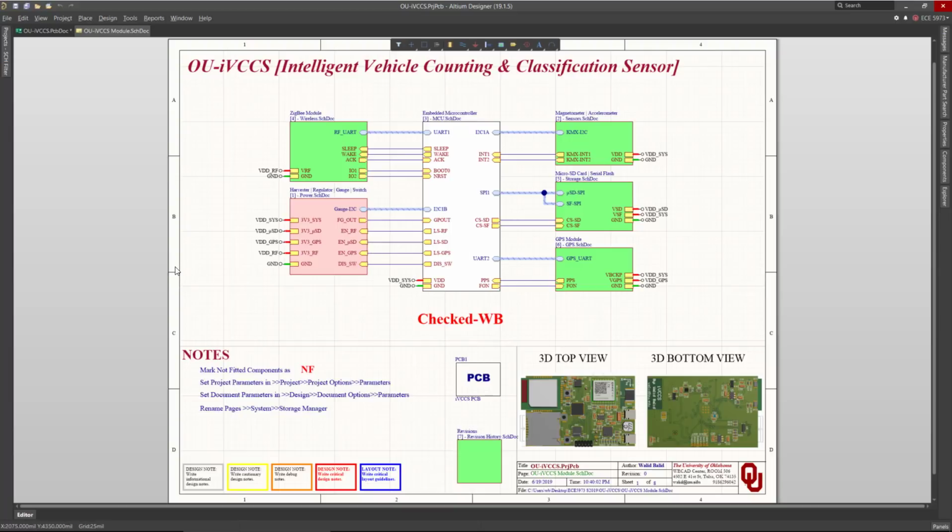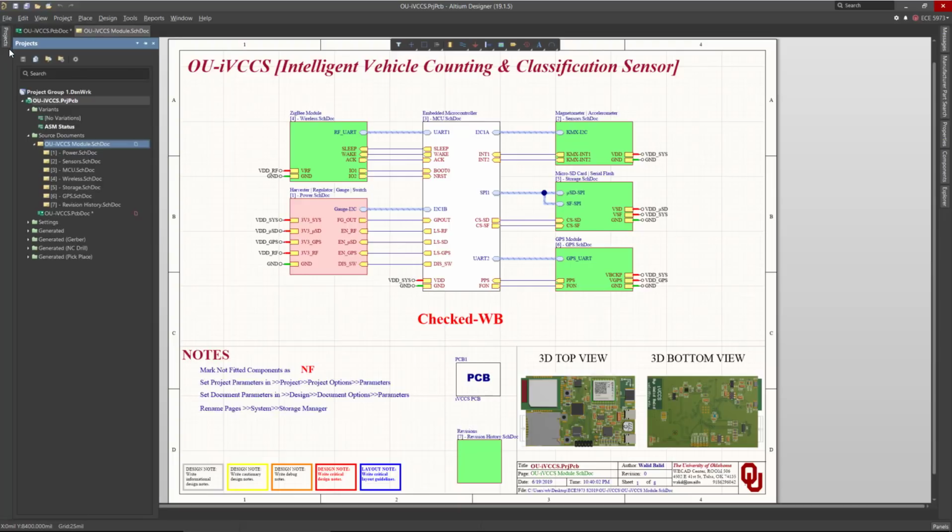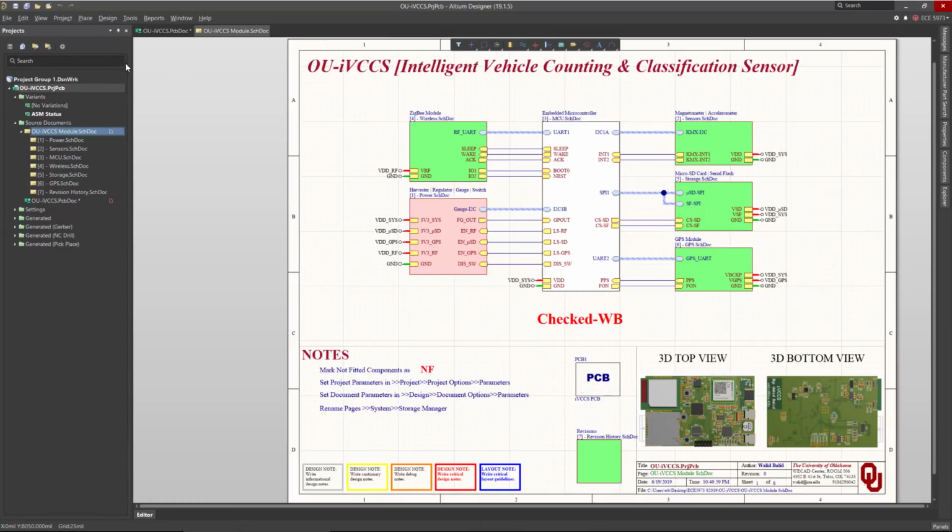Let's start with docked panel mode. These can be docked horizontally or vertically within the main application window. So if we click on a project in here, let's close the schematic. So let's make it in docked mode using this pin. So this panel will be always there. You can access it anytime. You can see the content all the time. Now, if you right click on it, allow dock, you can dock it horizontally or vertically.